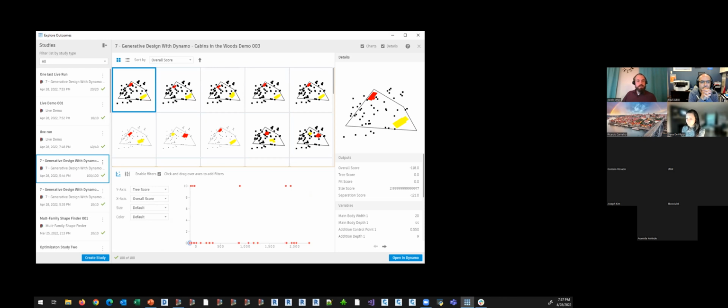There is a question here in the chat. Would you say the advice applies across all generative design processes? If you were using Fusion 360 for another use case in terms of constraints, constraints in Fusion 360 are very different from constraints in generative design for AEC, the generative design Revit toolset. Constraints in Fusion 360 are basically going to say, hey, here's where we can't put stuff, right? And that's going to inform the topological optimization or the tool pathing that is used to define that shape.